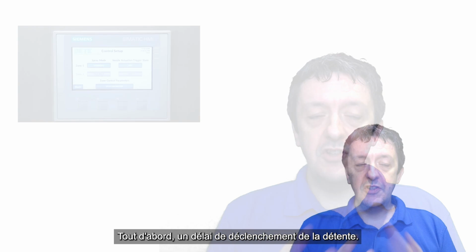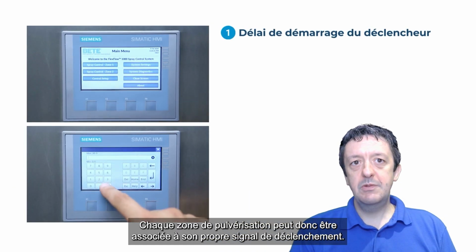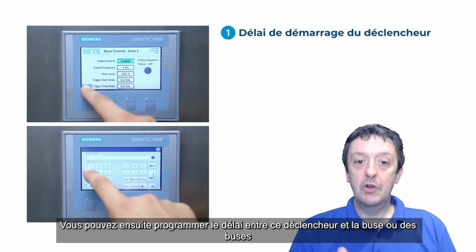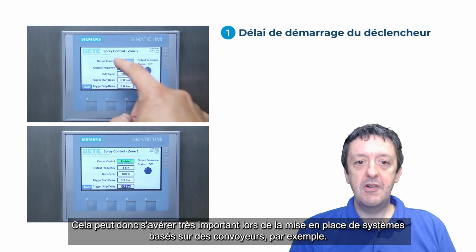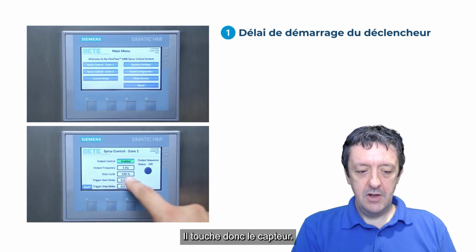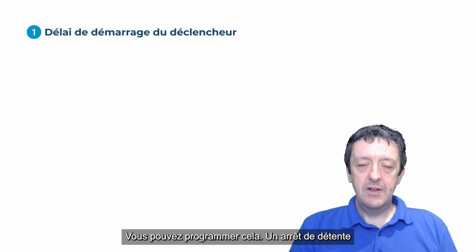First, the trigger start delay. Each spray zone can have its own trigger signal associated with it, and then you can program the delay between that trigger and the nozzle or nozzles starting to spray. That can be very important when setting up conveyor-based systems, for example. It hits the sensor, you want a short delay between that and the nozzle starting to spray, and you can program that in.